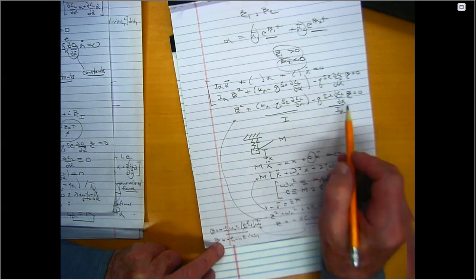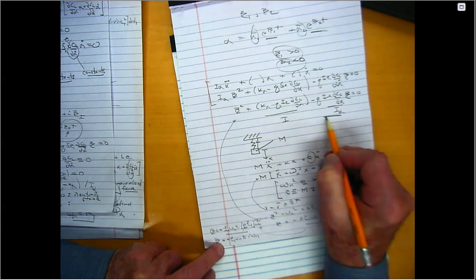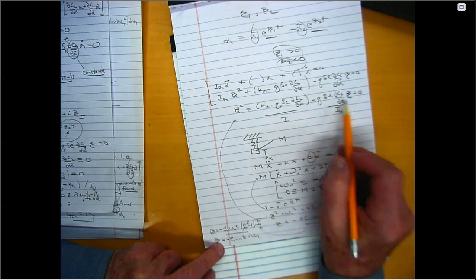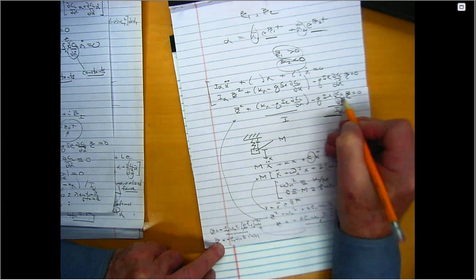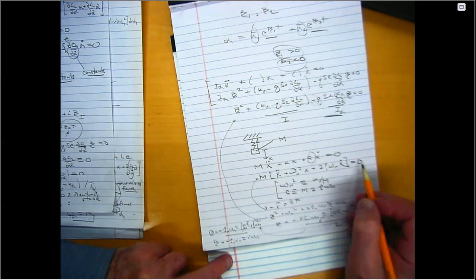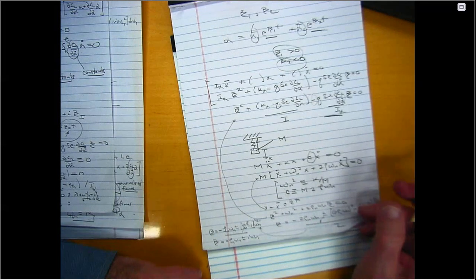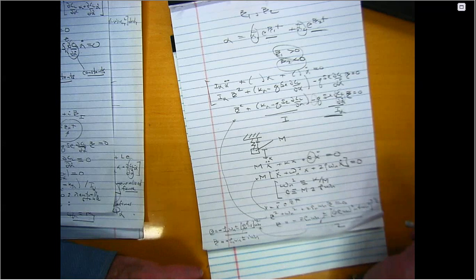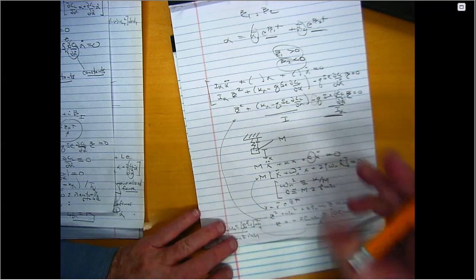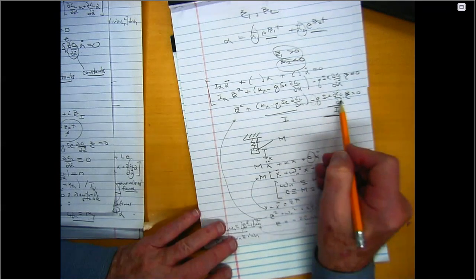But if I go back here and I look at this coefficient in this term, if this is a positive number, and I have a negative number here, then I have negative damping. That's the point. I have negative damping. And I can easily have that in an aerodynamic flow. The aerodynamic damping can actually be either positive or negative. And it usually depends on the value of Q, and this coefficient depends on Mach number.